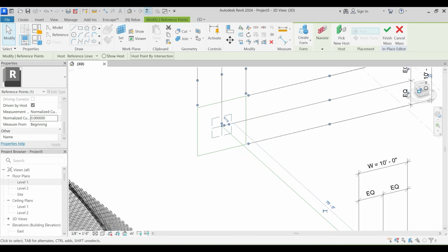family onto this. Okay, so File, New, Family, and this time I'm going to say family templates, English Imperial, and I'm just going to use this generic model pattern based family. And here I'll just quickly host a point somewhere over here, place on face, set work plane, select the vertical associated work plane to that polygon, and the same process that we did earlier. And just 1 to 2 and 3. Let me just first scale this down a bit. 1 to 2 and 3 and equal.